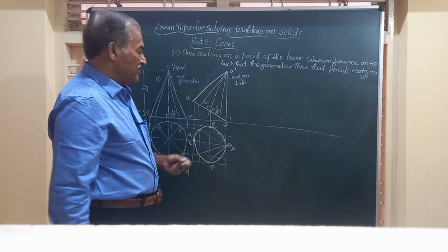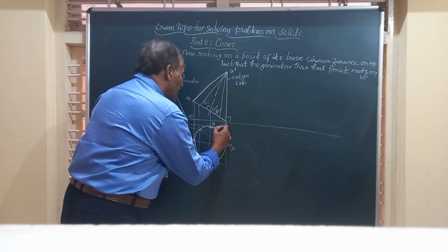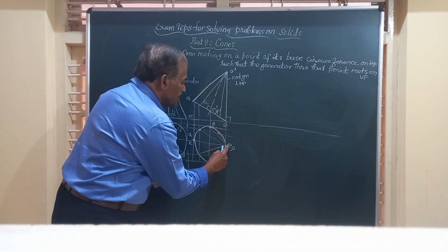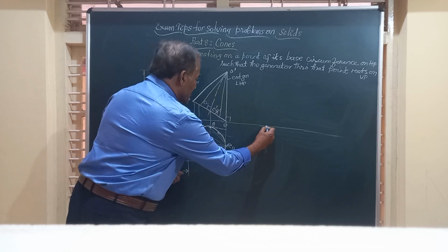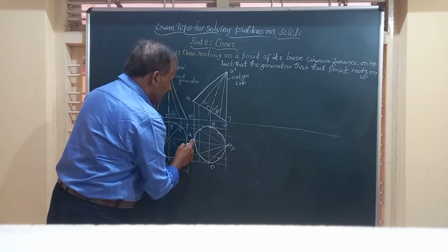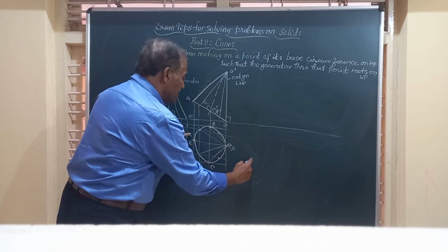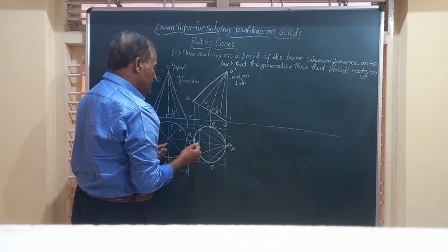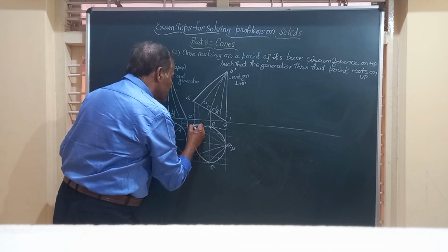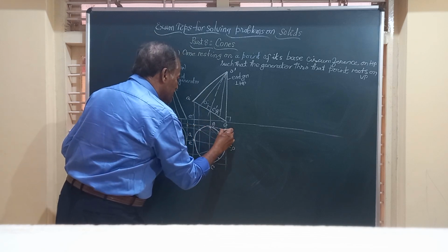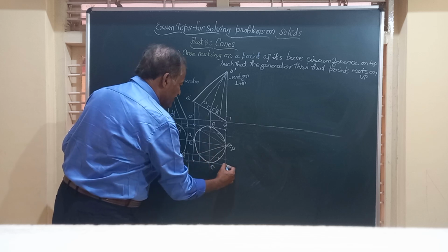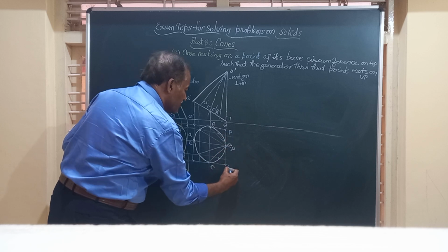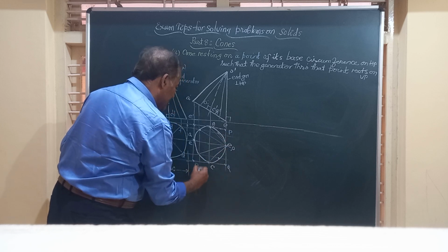Friends, now the point OE or the line OE is away from VP. It has to be on VP. That means to say, friends, I have to reproduce this figure such that this OE touches the XY line, and this A and the point E, A will be away from that. So friends, what is to be done for that is, I am going to enclose this ellipse in a box. We'll call that box PQRS. Say this is P, Q, R and S.